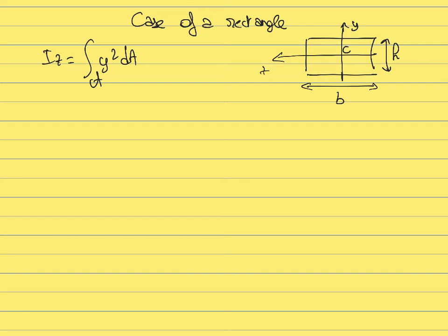If we want to do this, we need to take all the points M that belong to this beam, define the infinitesimal surface dA, which is equal to dy times dz in Cartesian coordinates, and then we need to solve this integral over all the points M that belong to this surface. So what we have to do is to take the integral over all the positions of this surface.